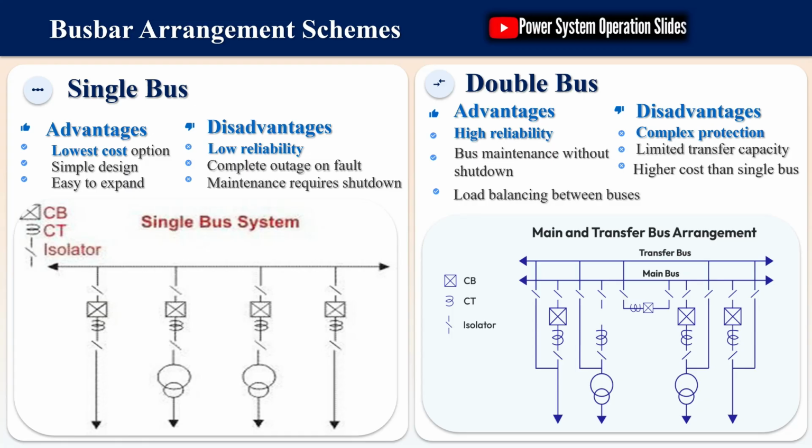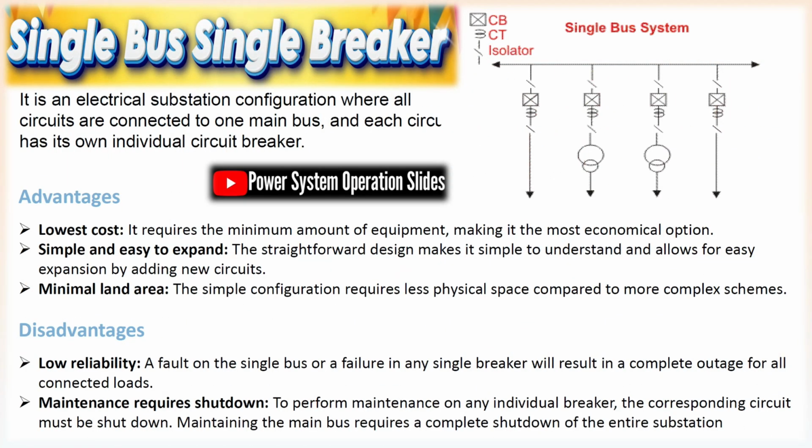Voltage transformer, VT. VTs step down high voltages for safe metering, protection, and control. They provide accurate, isolated secondary signals. VTs enhance safety and enable precision monitoring of HV systems.